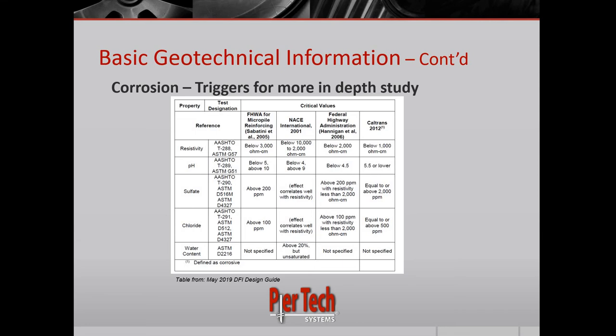So it's good to have galvanized piles in there, or maybe even encapsulate that pier with a concrete sleeve near the surface where you have that fluctuating groundwater level. All these are very important for looking at for more in-depth studies. And if you get into this, you'll want to make sure the geotech engineer understands this aspect of it, and you may have to hire a special corrosion engineer for a project that's in one of these areas that is very susceptible.